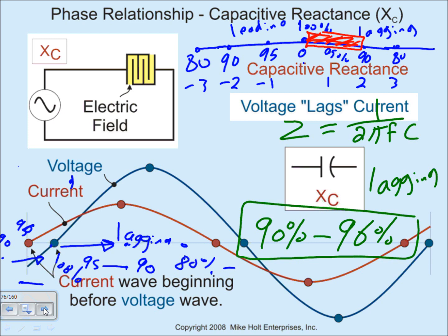You definitely don't want to be here or lower than that. Lower than that you can be, but you have to correct. Higher than that you can be, but you have to correct. Believe it or not, utilities and transmission lines sometimes find themselves with a 95% leading power factor. You know what they do? In order to correct the leading power factor, they install reactors, coils, in their system so they can increase the reactance. So the optimum design is right in this area. Good point though.